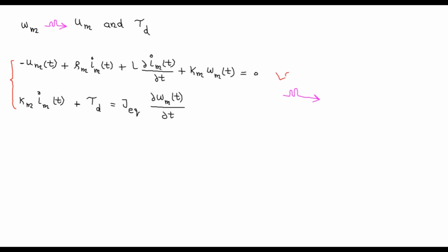Now let's find the transfer function for the system. To do so, we need to go to the Laplace domain. Here's what we get if we apply the Laplace transform. The derivative will be replaced by s.